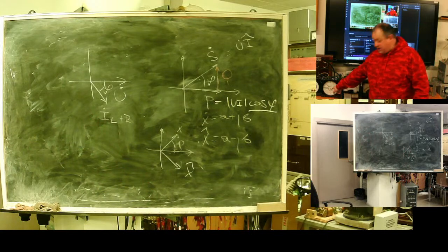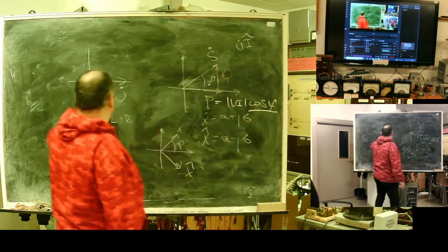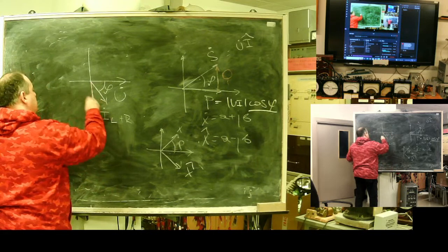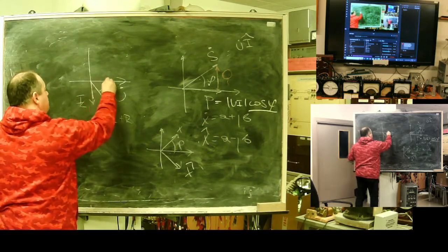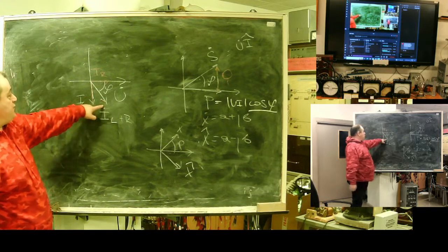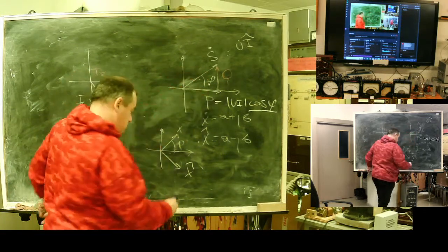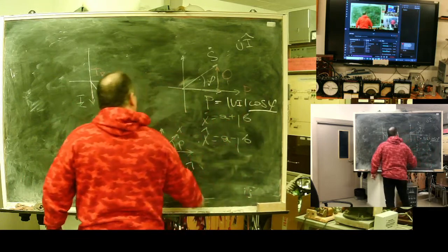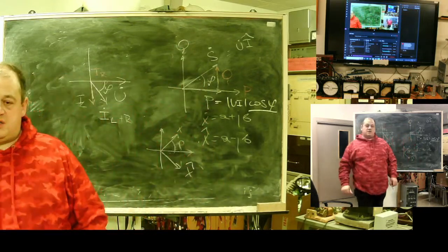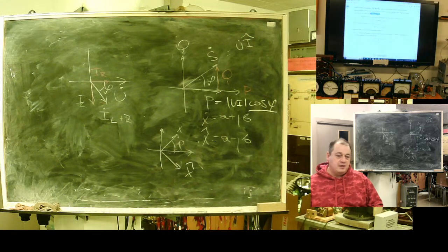Here is written power factor, and it's the cosine of the angle between the, I had this coil current, I have this active current, their sum is a full current, and the full current multiplied by voltage gives the apparent power, projection to the real P, and imaginary Q. Coil assumed positive, capacitor assumed negative. It's just an agreement.